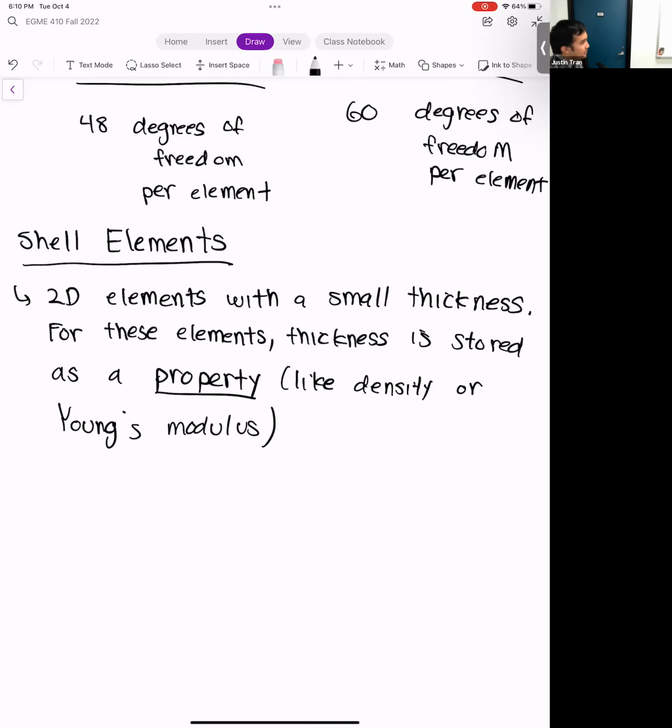That wasn't exactly a shell element because that surface was just a dummy surface, but it was implemented as one, and so that's why we had to specify the thickness. We didn't actually do anything with that thickness, and that application surface didn't have any structural strength, but that's the idea. Whenever you have a shell element, you have to specify what that thickness is before you use it.